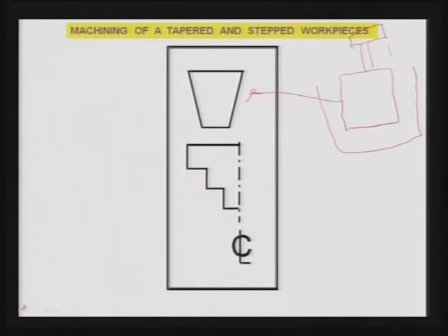Let us make another figure, like this, and it is filled with the etchant, and you take the workpiece like this, and there is a control over here. Now you start moving the workpiece downward at a very low rate, that you have to decide with the help of preliminary experiments, and as you keep moving it, the material will keep removing.